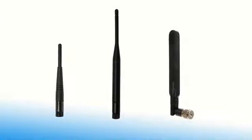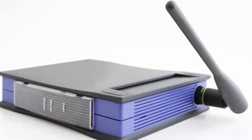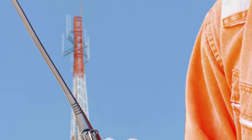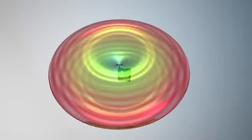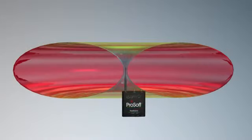The most common omni antennas are whip antennas, both the straight and articulating variety. They do not require a ground plane and are typically connected directly to the radio enclosure. This type works well with belt-mounted remote radios or other applications where mobility is a factor. This type does not radiate well out the top of the antenna and thus must remain vertical.